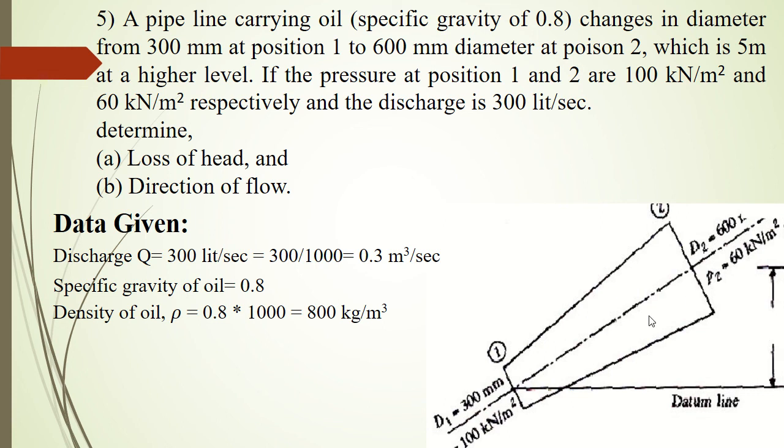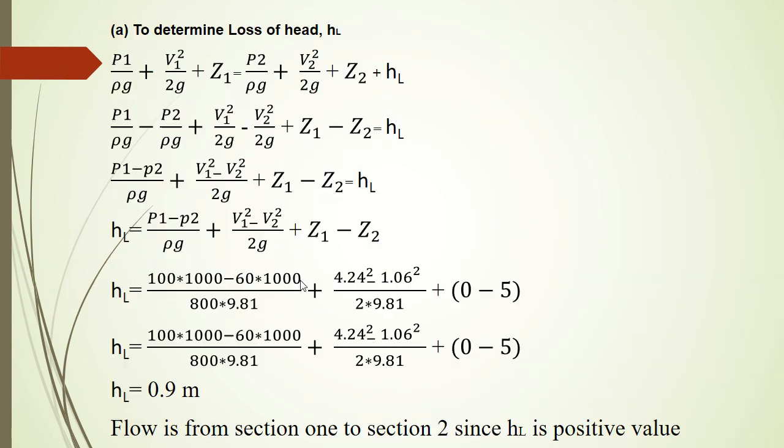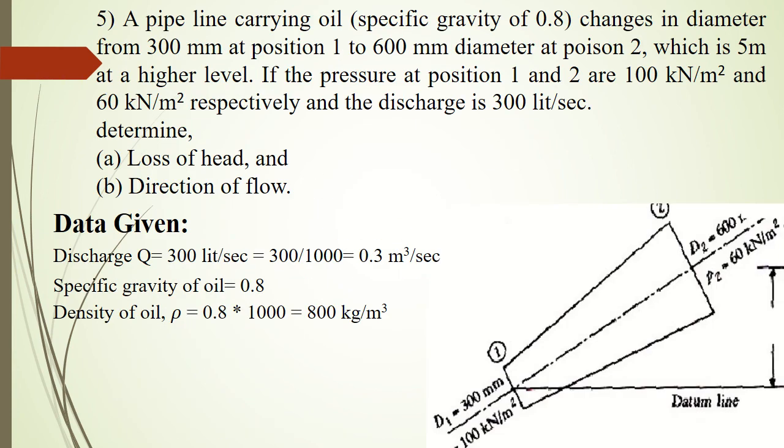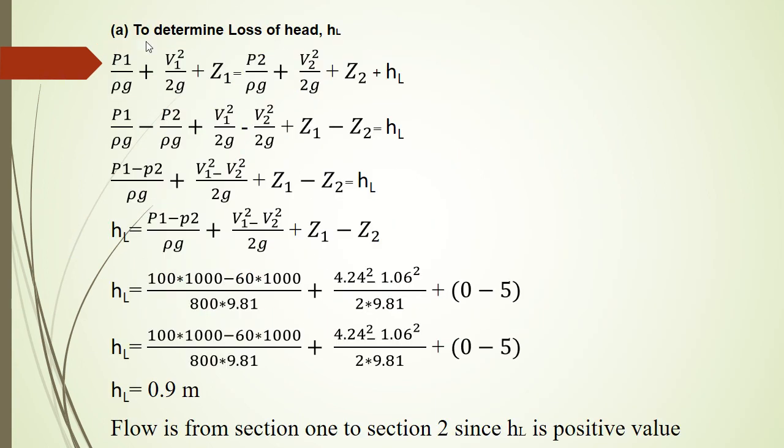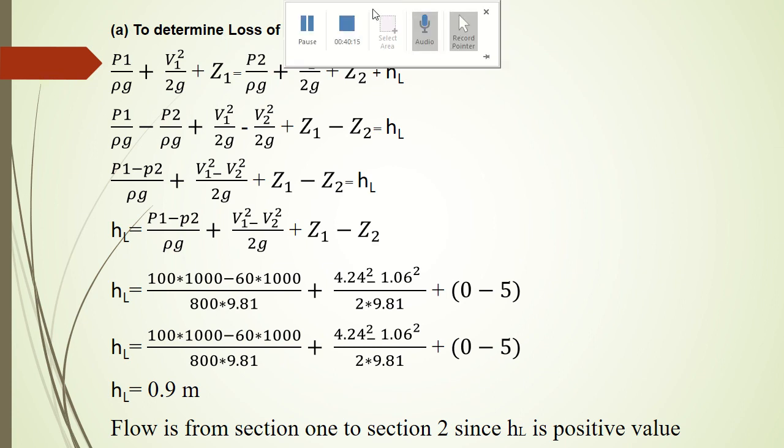And one more thing here: if the loss of head is asked to be calculated, then you have to make use of Bernoulli's equation applied for real fluid, that is this. You just have to add the loss of head at the end of the formula. It is all the same, this is the extra term you get in the formula.